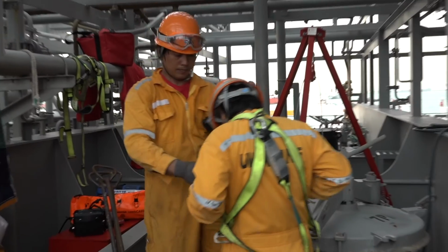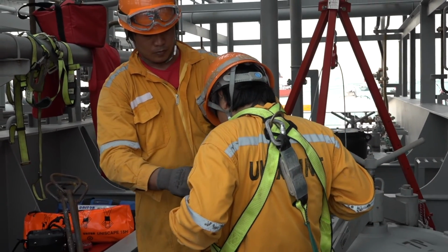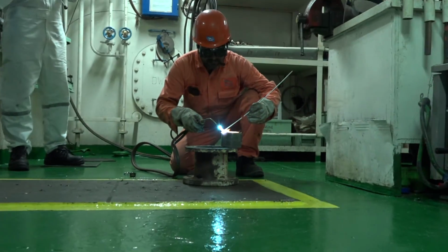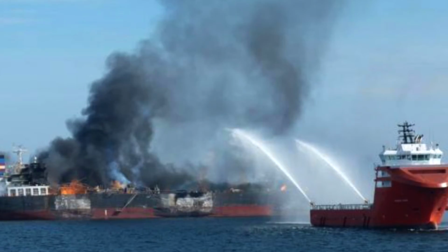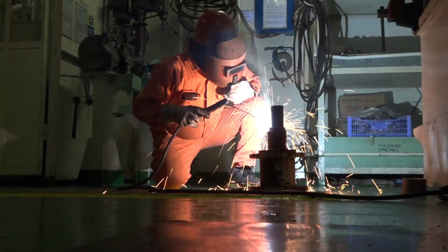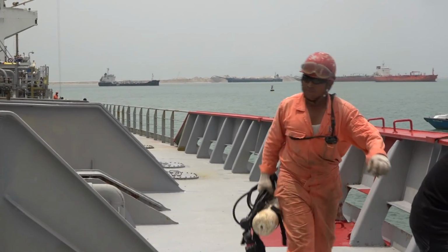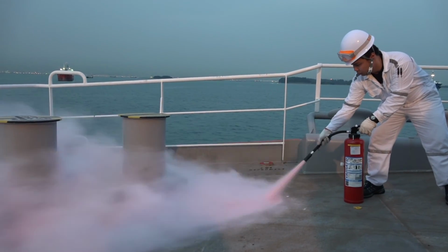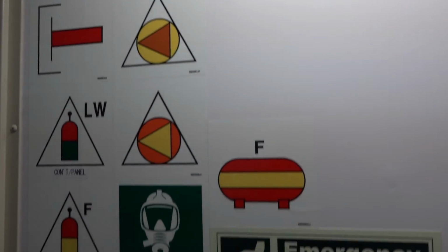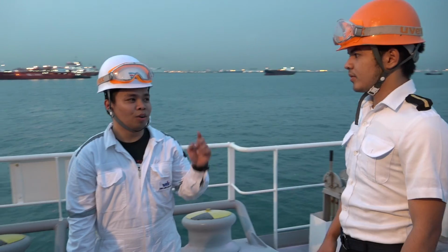The most common example of this interaction is an ignition source in the presence of flammable vapors, leading to an explosion and fire. The hazard identification process needs to account for this interaction between energy sources, as many incidents can be attributed to a combination of unexpected factors that only seem obvious in hindsight.